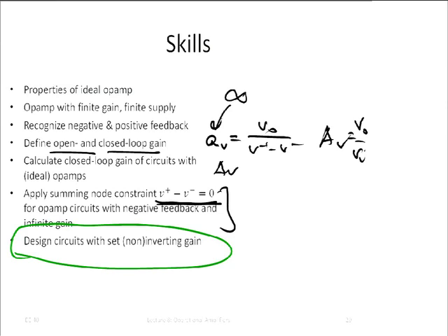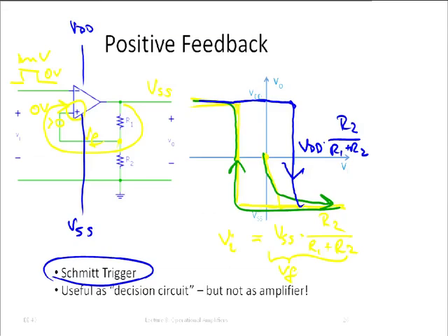And if they come, yes? You did a good example on negative feedback, but what assumptions do you make when you have a positive feedback system? Yeah, unfortunately, if you have positive feedback, the difference of these voltages is no longer zero, and then you have to analyze it by inspection, like I did.